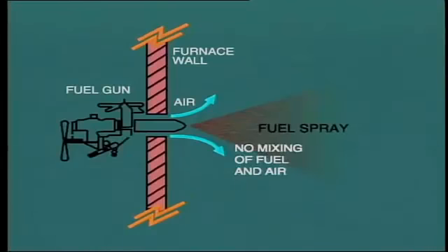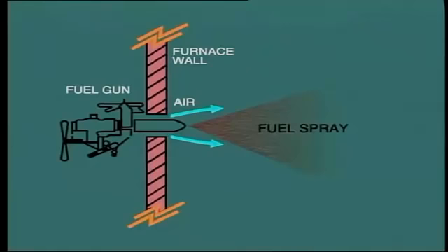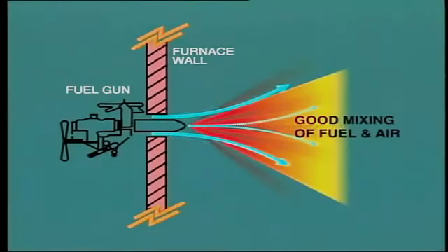It is vital that the air comes into intimate contact with each tiny element of the fuel. In order to ensure this thorough mixing, some form of turbulence is created as the fuel and air enter the boiler through the burner equipment. Even when the fuel and the air are ignited and thoroughly mixed, a certain amount of time is required before the combustion process is completed.